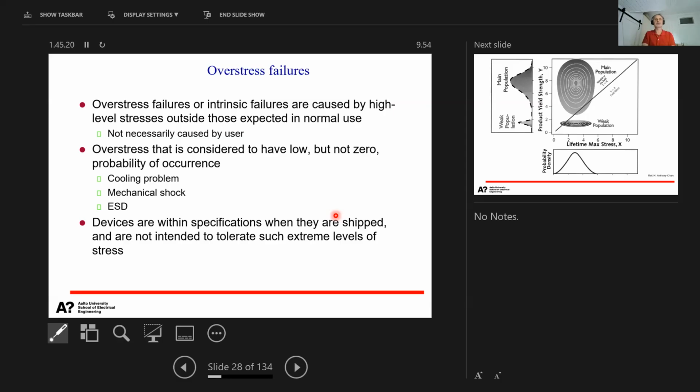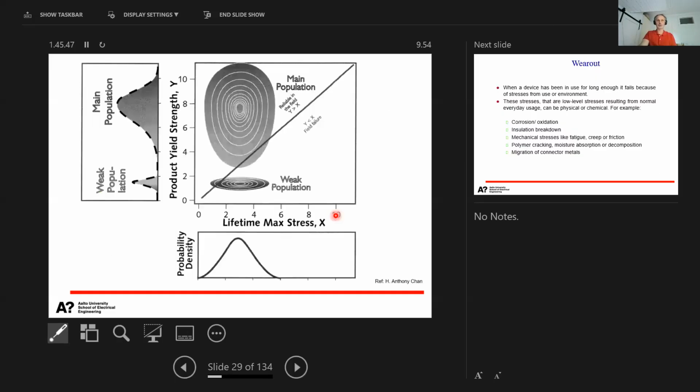And that is extremely small. Even if one airbag fails during the 10 years of operation of the car, that causes severe problems to the manufacturer. So we need to push these overstress failures as small as possible. This comes back now to the robustness of the system.